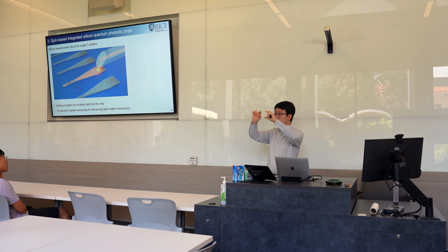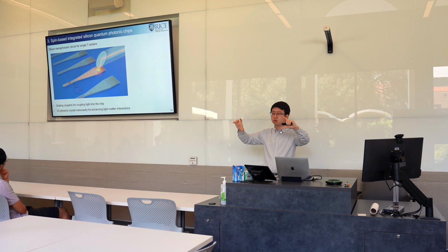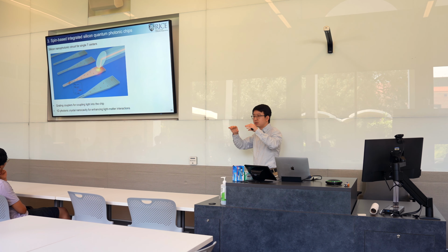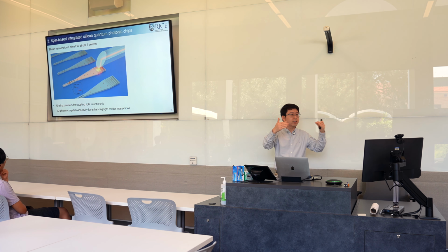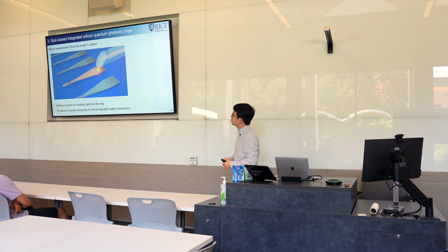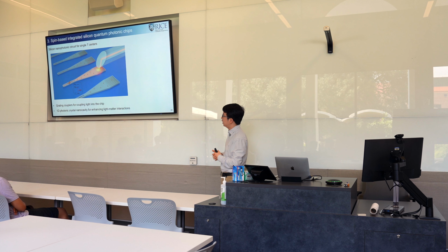So you have a very thin silicon device layer, about 220 nanometer, on an oxide, which is typically on the order of like 2 micron. And then you have the substrate of silicon. So this is called SOI. So we fabricate the nanophotonic structure on the device layer, and then we pattern it, we etch the device, and then this is what we are using now in the lab.